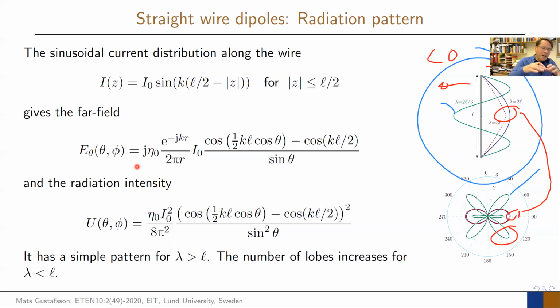So the radiation pattern of your antenna depends basically on how complicated your current can be on your structure, and then the distance from different pieces and what that phase difference is. And when the antenna is small, not much can happen. But when the antenna gets longer, a lot of odd things can happen, and that creates a radiation pattern that starts changing. We will see much more about that later in the course.